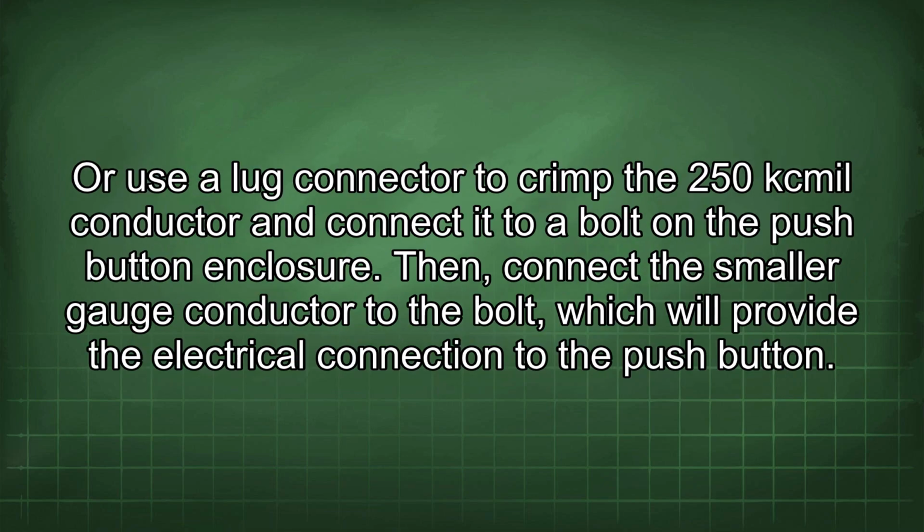Or use a lug connector to crimp the 250 kcmil conductor and connect it to a bolt on the push-button enclosure. Then connect the smaller gauge conductor to the bolt, which will provide the electrical connection to the push-button.